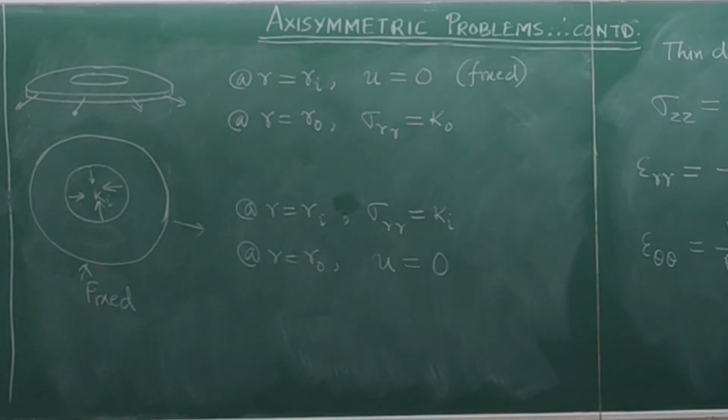So we can have a variation of these problems where we say that maybe the internal pressure is this, and find out the external pressure such that the sigma rr at such a radius does not exceed the allowable stress. Ultimately you have to go through all of these steps only, but you be careful about what we are asking for.